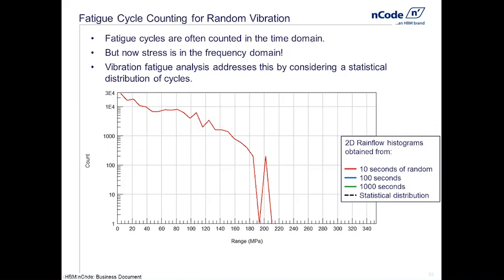Keep in mind, the reason we're talking about the frequency domain here is that if we do everything in the frequency domain with steady state dynamics or harmonic stress solution in FEA, the beauty is that the stress results are very compact. We end up with what we call a stress PSD, and that stress PSD needs to be cycle counted in some way. So we end up looking at a statistical approach to cycle counting, as opposed to a deterministic approach that we use in the time domain.